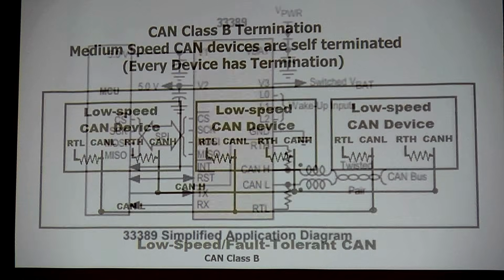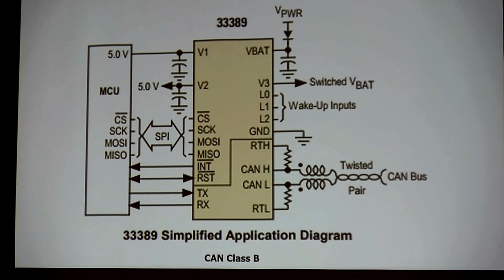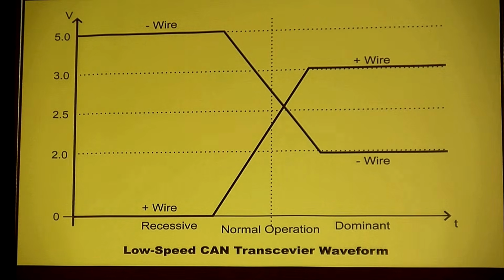That's why it's done. This is one of the systems we can see right here where we've got our twisted pair. Over here, we come in to the system. Note my termination resistors. Note you still have to have termination resistors, don't you? Because without any termination, we have ring echo. Echo is the right word to refer to it. So here we have this system.